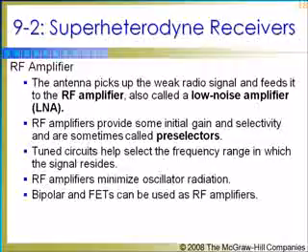The local oscillator signal is relatively strong, and some of it can leak through and appear at the input to the mixer. If the mixer input is connected directly to the antenna, some of the local oscillator signal radiates, possibly causing interference to other nearby receivers. The RF amplifier between the mixer and the antenna isolates the two, significantly reducing any local oscillator radiation.